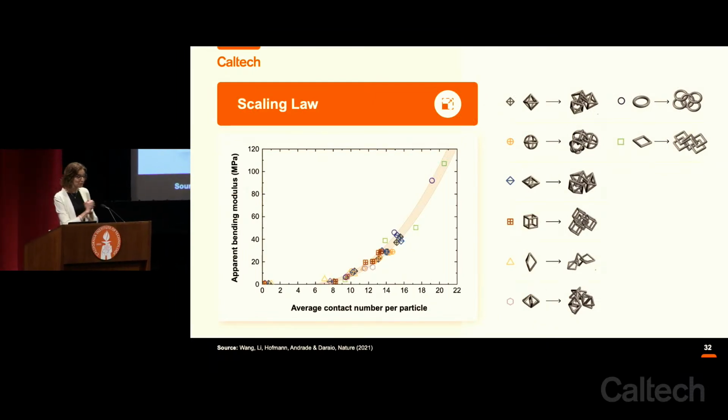So first of all, yes, and the stress and strain relationship of this jamming transition depends very much on the particle geometry, and not just the particle geometry, but also how the particles are linked with one another. You can take, for example, ring particles and connect them in multiple configurations. That will affect how much stress and strain the material is able to support with different loading conditions, whether you shear it, bend it, pull it, compress it, and so on.